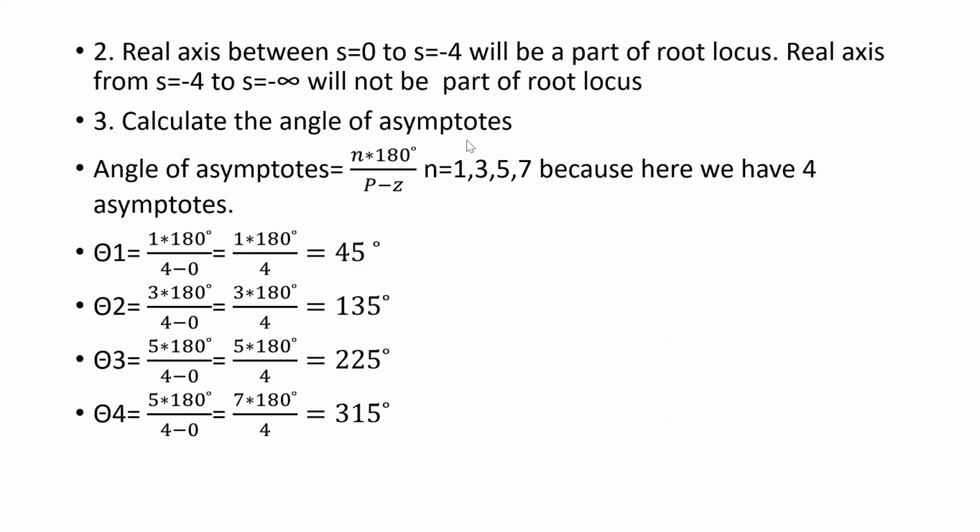So now how many poles do we have? We have 4 poles. Do we have a zero? No. So there is no zero for it to end directly. But it will end. Where will it end at a zero? At an infinite value. Somewhere, if I have a pole here, I'll assume that there is a zero somewhere at infinity. So this is very far. But from here to here, the root locus will start, and it will start moving towards this zero.